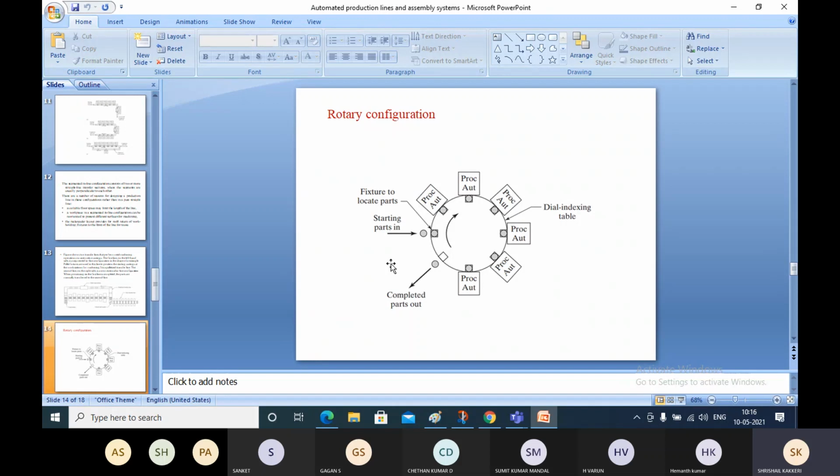So this is totally automated. And in some other cases, wherein very limited space is available, the work part is to be transferred. And please remember one other important point I wanted to tell you: where the work parts are heavy in structure, just like engines, with a very heavy base part on which small parts are to be arranged, at that time the inline processing workstations will be very much useful.